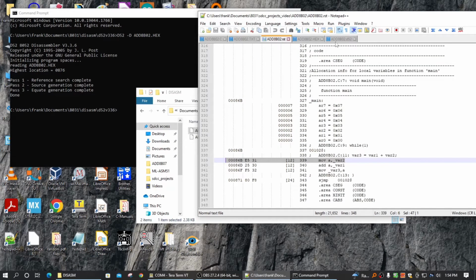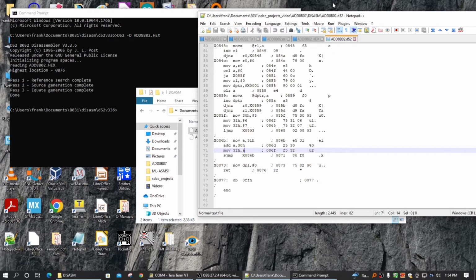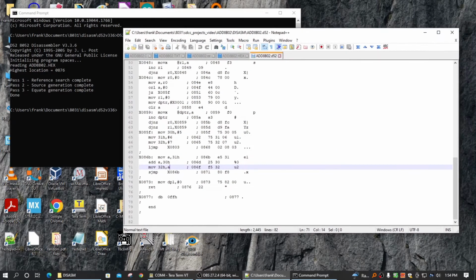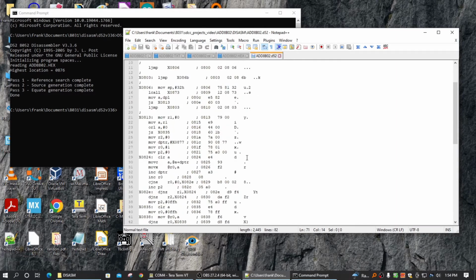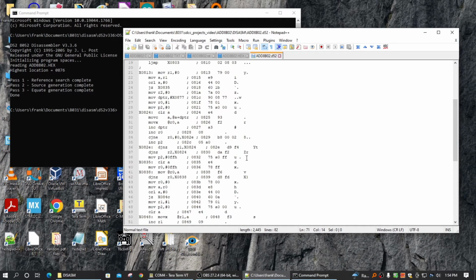It's the same instructions, but what you can see that you can't see completely in this RST file is there's a lot of overhead in the compiler. There are a lot of jump arounds, like it jumps in at the origin and makes space for interrupts and stacks. It makes a lot of space for things that this program doesn't even use.